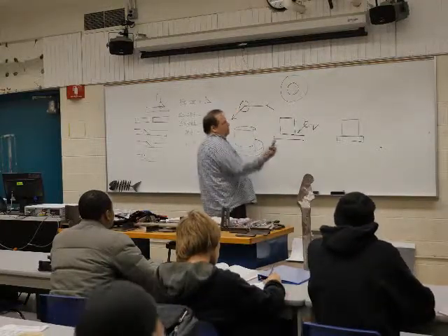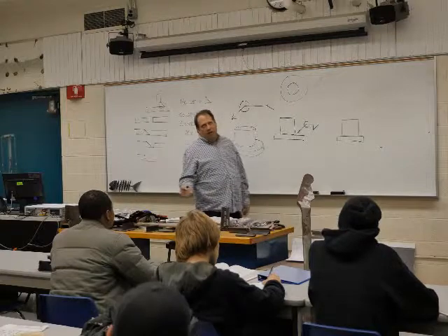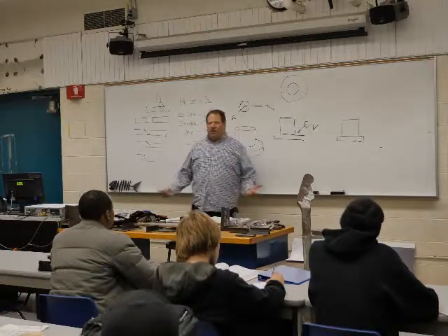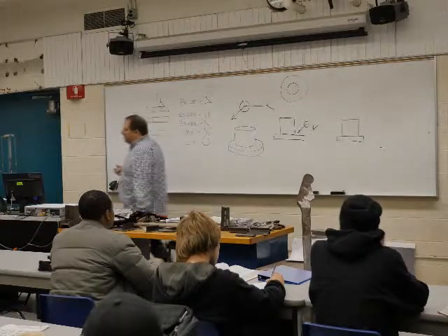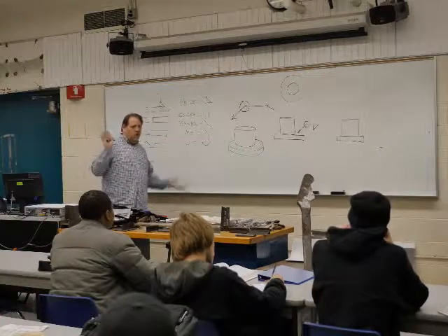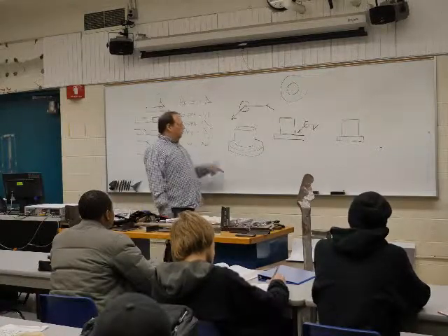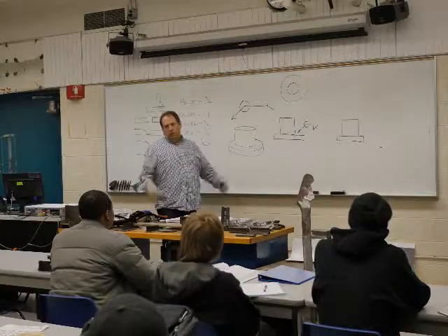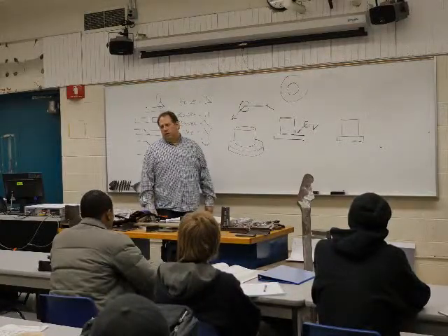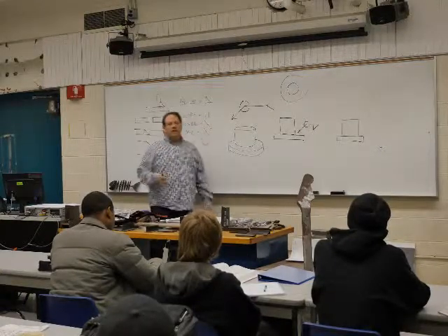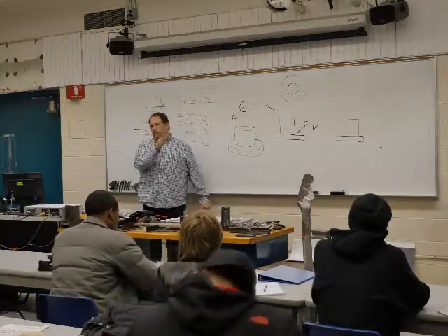Except for maybe the idea of where to start, but really where to start and where to end isn't that big a deal, unless there's something critical on where the starts and stops have to be. Other than that, it's not really critical. We can start anywhere around this thing. As long as that weld is good all the way around, it doesn't matter where we start or finish. It's still welded all the way around. Okay? So think about it in that sense: with fillet welds, we're going from left to right.